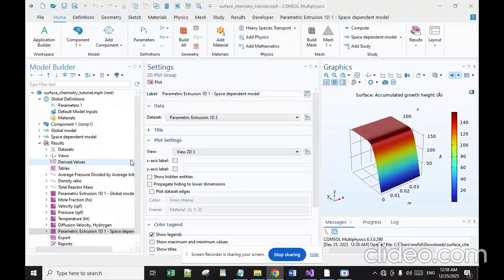Phosphorus oxide in high concentrations interacts with ambient moisture to produce phosphoric acid. Crystals of BPO4 can also precipitate from the flowing glass on cooling. These crystals are not readily etched in the standard reactive plasmas used to pattern oxides and will result in circuit defects in integrated circuit manufacturing.